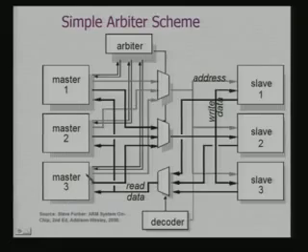So the whole thing can actually be overlapped in time. If you look at it, the basic picture is something like this. I have a central arbiter. These are multiple masters sitting on the bus. They will generate the request and the arbiter will generate the grant once it resolves the priority. If there are multiple requests coming in at the same point in time, the arbiter will use its own priority scheme, which we had discussed in the last class, to identify which master now gets the bus. Once it knows, it enables these buffers.